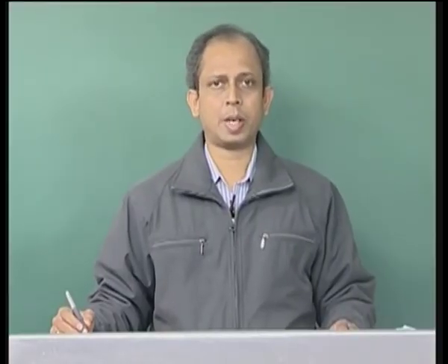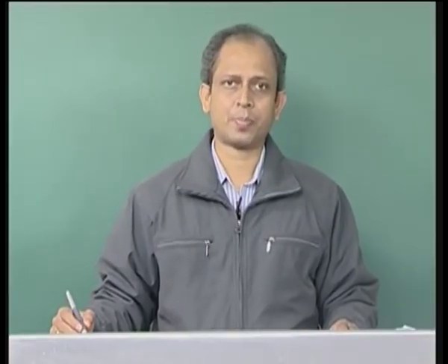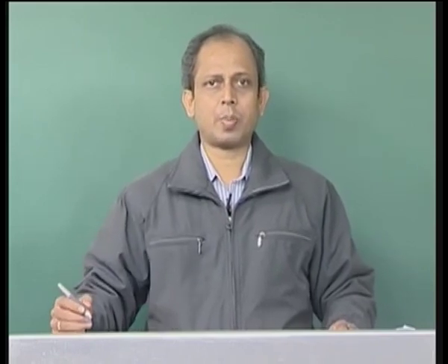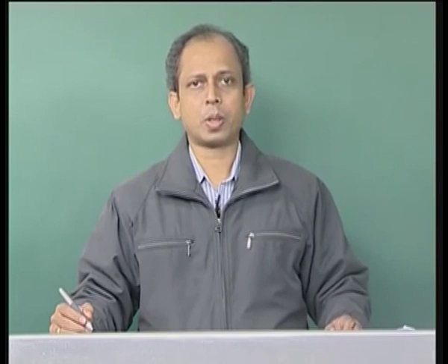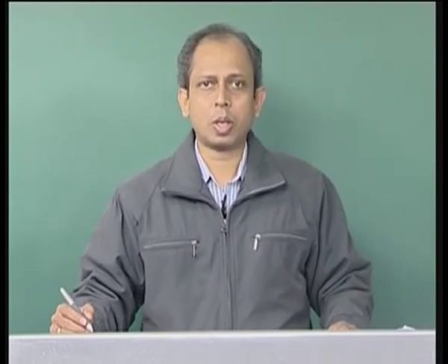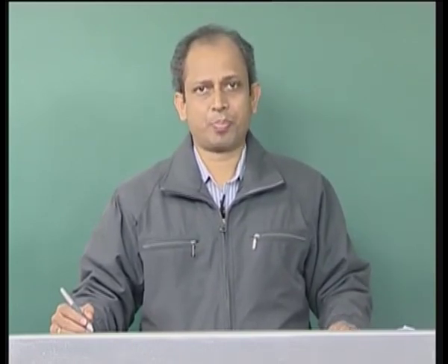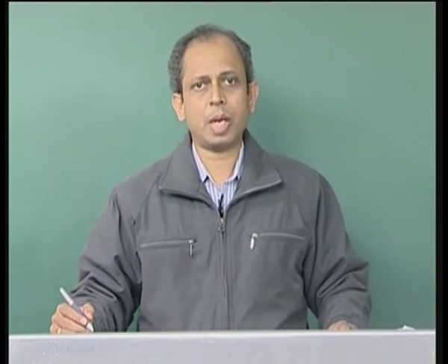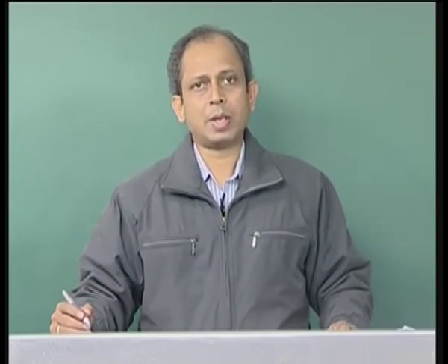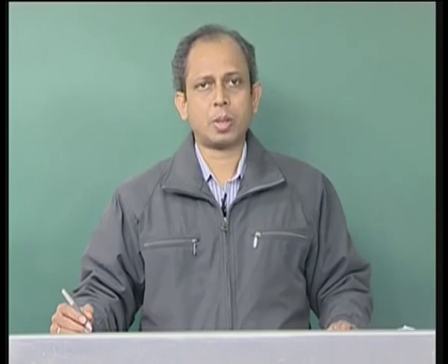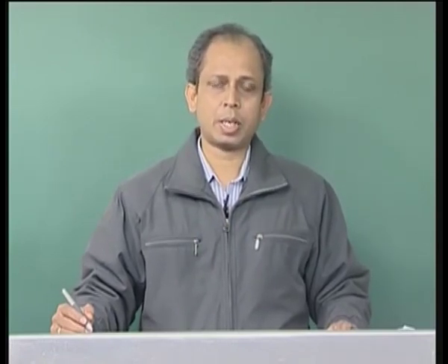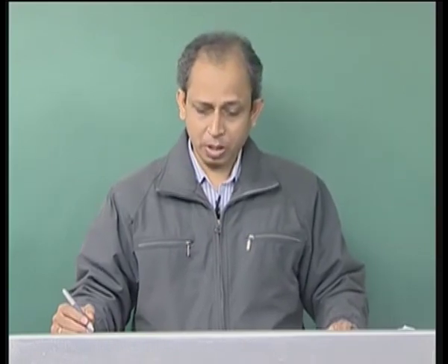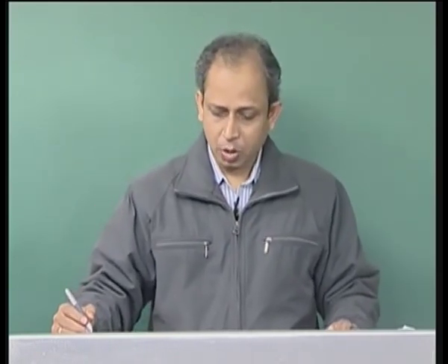Hello and welcome to this lecture on advanced electric drives. In the last lecture we discussed the sinusoidally excited permanent magnet synchronous motor, or in brief PMSM. In a PMSM, the windings are distributed sinusoidally and the back EMFs are also sinusoidal.